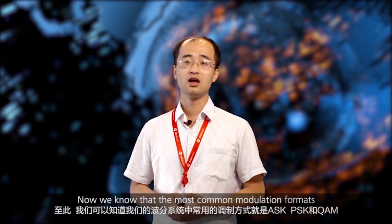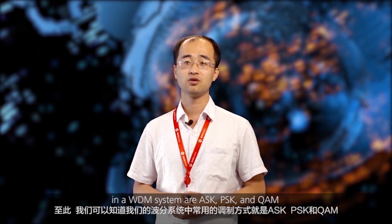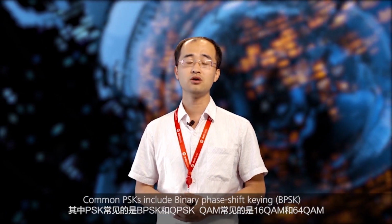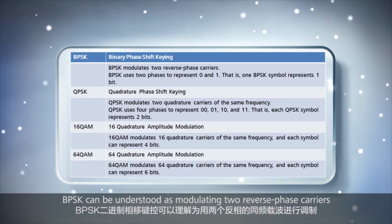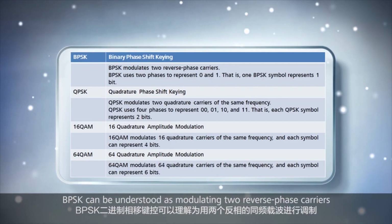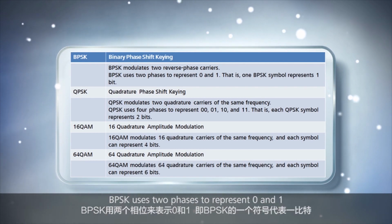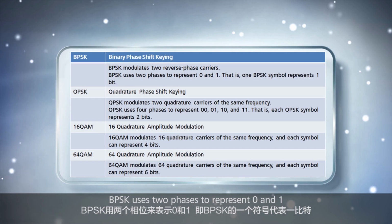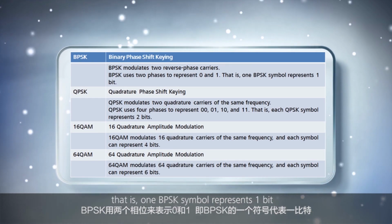Now, we know that the most common modulation formats in a WDM system are ASK, PSK, and QAM. Common PSKs include binary phase shift keying and quadrature phase shift keying. Common QAMs include 16 QAM and 64 QAM. BPSK can be understood as modulating two reverse phase carriers. BPSK uses two phases to represent 0 and 1. That is, one BPSK symbol represents one bit.